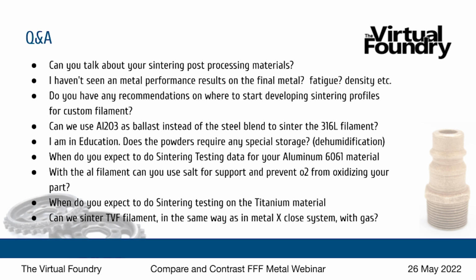Beyond that, the sintering properties of just about any material you can think of, you can find in a research paper. So start digging around. A good place to start your analysis is a sintering temperature of 80% of the melting point. So use the profile that we've published on our website, but adapt the sintering temperature to be 80% of its melting point.